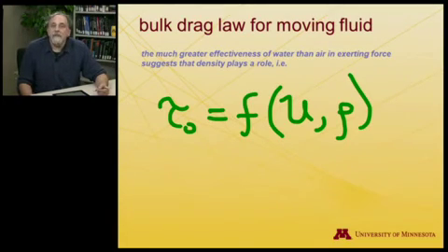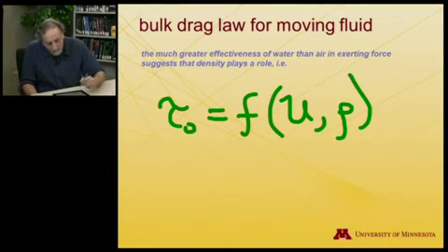So you could apply the Buckingham pi theorem that David talked about in class to this and work out what kind of relationship this must be. In fact, the derivation that David did for settling spheres is actually not too different from this. But if you just look at the units of these, you can actually pretty well work out what kind of relationship it has to be.